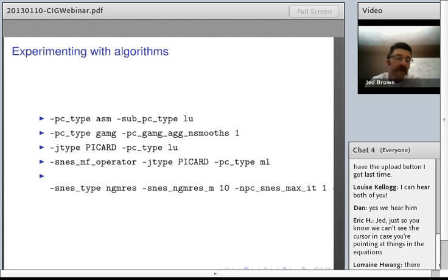And then we'll precondition it using this Picard linearization and, say, algebraic multigrid from ML. And we'll see that that does converge quadratically. So as we turn on any of the nonlinearities, that will still converge quadratically, which is a very attractive feature. And it's much less expensive because the Picard linearization doesn't have nearly as many non-zeros.